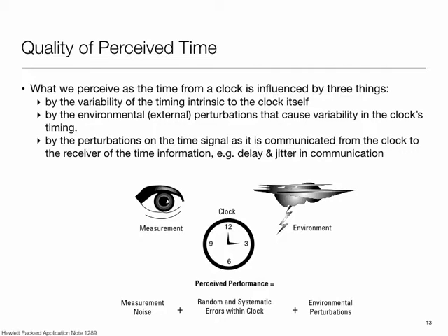Second, the counter that the OS is maintaining is going to be at some granularity. It's updated at some period, so that's a quantization error that kicks in. Thirdly, the way these things work is that the counter, a software variable, is being periodically updated by a hardware counter, which in turn is being driven by some clock.